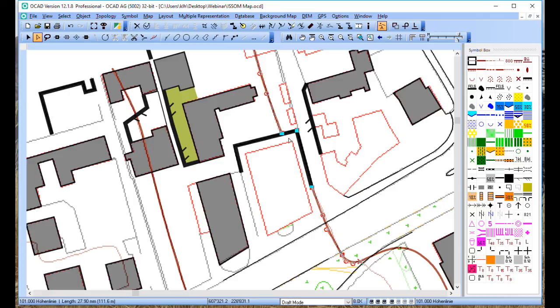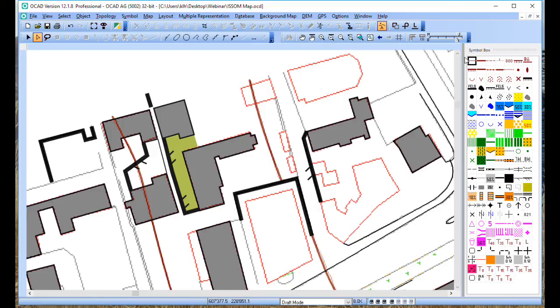This is especially important if you have some passages beside that, so it would be very bad if you draw contour lines along small narrow passages like this, because this has a very bad impact on the legibility of the map. Here, contour line should be drawn on one side of the passage. So with this, I'm at the end of this section about drawing.